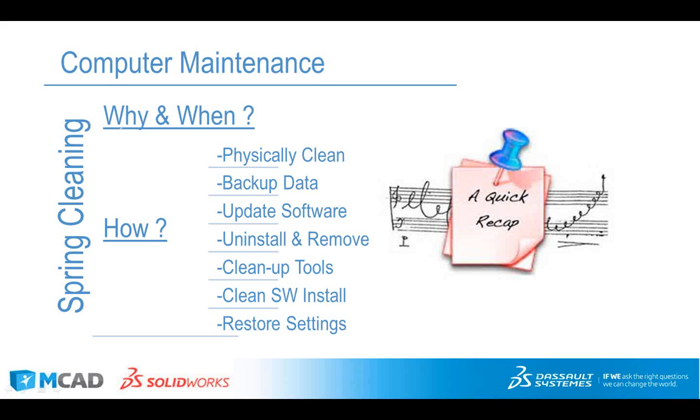And when that's done, just like we saw, you want to restore everything to get it to function the way you're used to. So these are some general topics, definitely worth giving that a try. You'll be surprised at how just cleaning the temp files out periodically can definitely have a big effect on performance. And just saying again, because it's important, check the graphics card driver combo. Many problems can be caused by the incorrect driver.